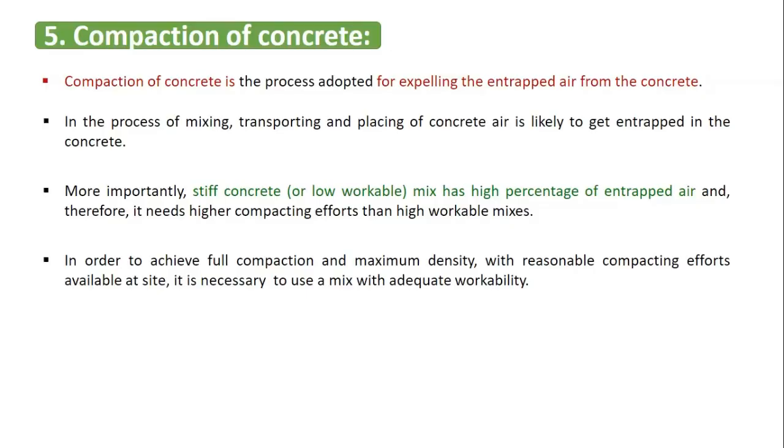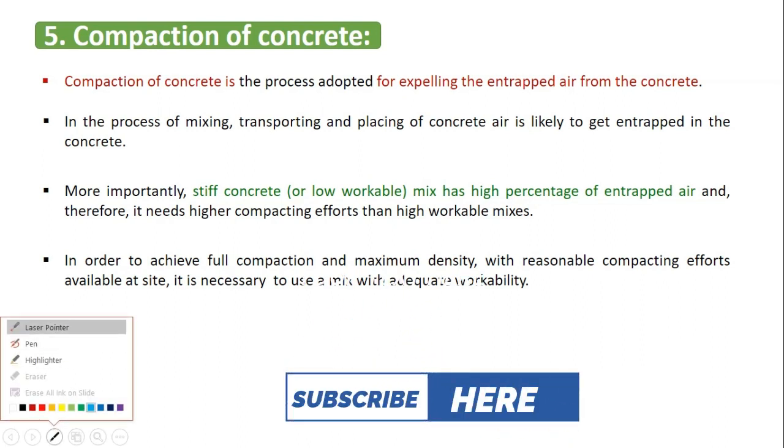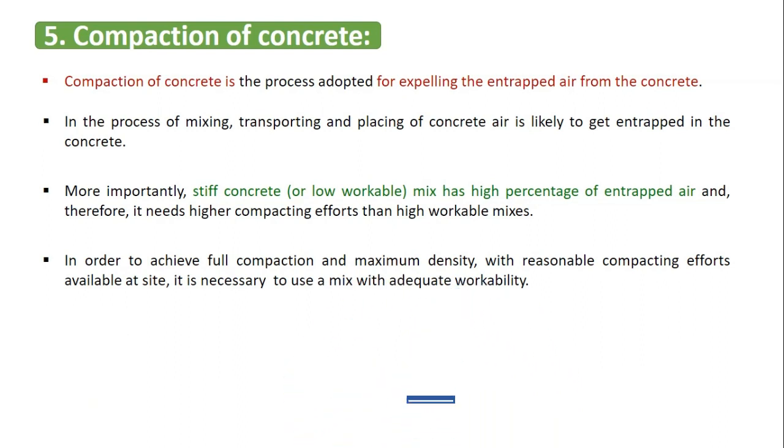In this video, we are going to see step 5, that is compaction of concrete. What is compaction? Expelling the entrapped air from the concrete. When we are mixing the concrete, transporting the concrete, and placing the concrete, the air from the atmosphere is going to get entrapped in the concrete.